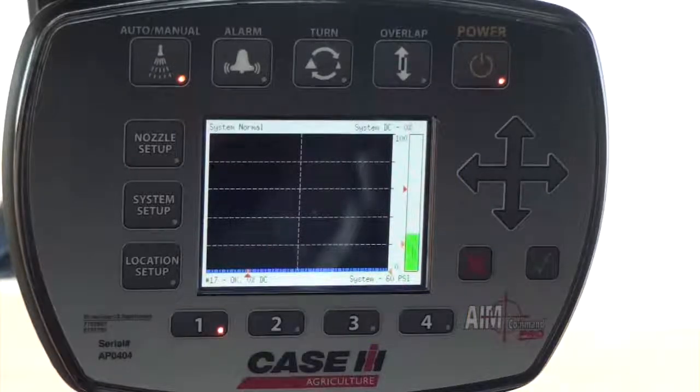There is a volume of information on the screen as well. System duty cycle is seen in the top right corner. This is an overall measure of the system duty cycle, and depending on field operating conditions, this will vary. System status is at the top left corner, and this is where we will see any faults. Missing VCMs, no GPS, and other serious system faults will show here.